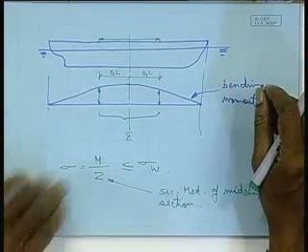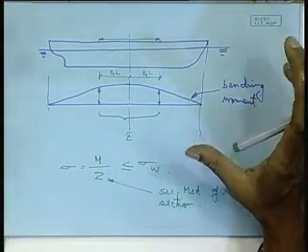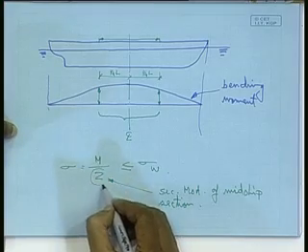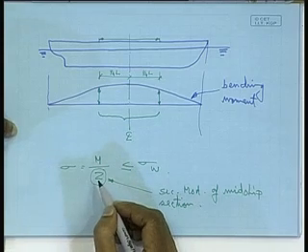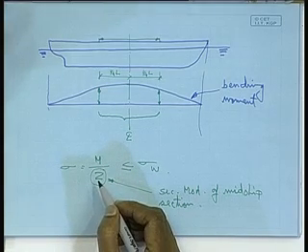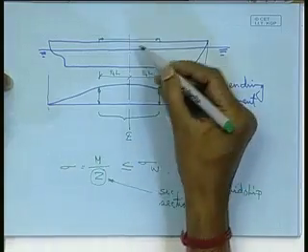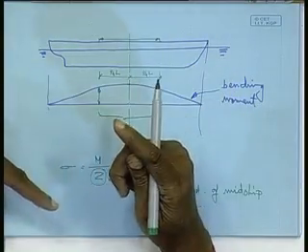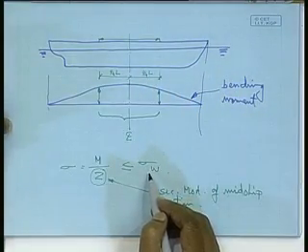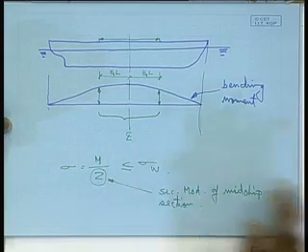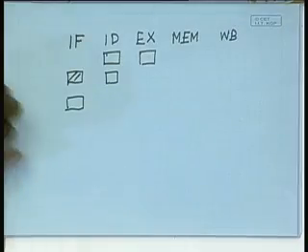So that is how midship section is an important drawing, from which we calculate the section modulus and ensure that for a given loading condition, or for the fully loaded condition and in the worst case scenario of wave loading, the stresses coming on the deck as well as on the keel, because they are the farthest members, remain within the permissible stress or the working stress, right. So that is essentially the importance of midship section.